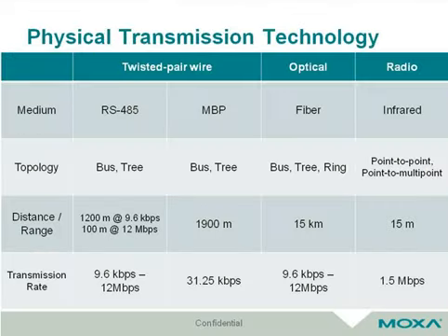There are three kinds of media which can be used for PROFIBUS: the twisted pair wire, fiber, and infrared. RS485 transmission is the transmission technology most frequently used by PROFIBUS. The application area includes all areas in which high transmission speed and simple, inexpensive installation are required. The transmission rate is from 9.6 kilobits per second to 12 megabits per second, which can meet most cases.